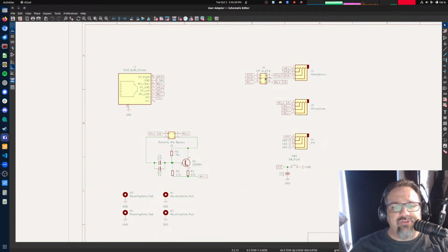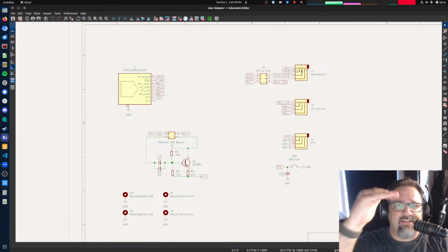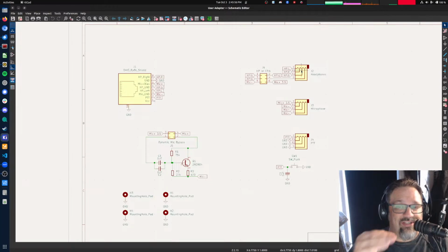Then there will be some jumpers that you can use to configure whether headphones are just standard 3-pin TRS headphones, or whether it is a 4-pin CTIA style, like the TRRS, the 4-pin connector that is common on PCs now, used to be common on laptops, on mobile phones. It's called the CTIA standard, but I sometimes call it the PC gaming headset standard. Anyway, it is tip is left, the first ring is right, the second ring is ground and shield, and then the sleeve, the fourth connector, is the mic plus. And then all the headphones and the microphone share a ground.